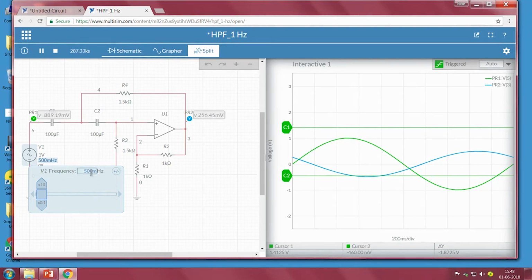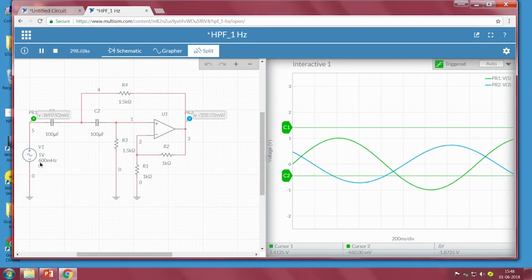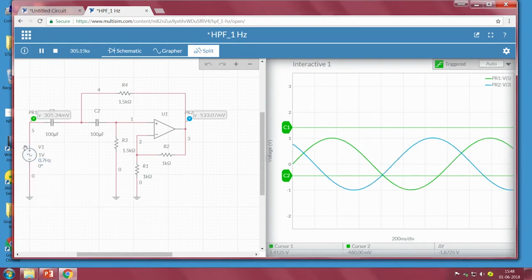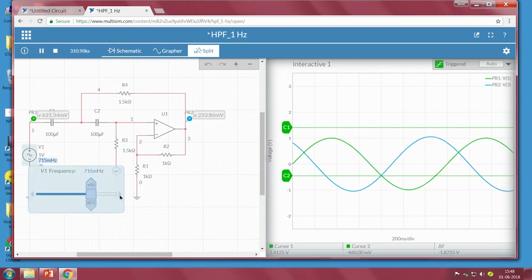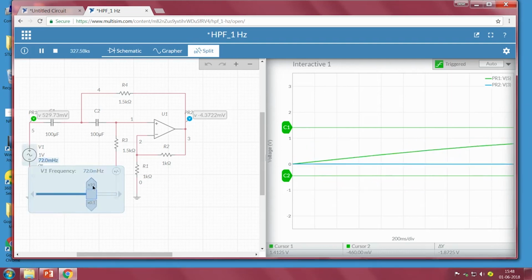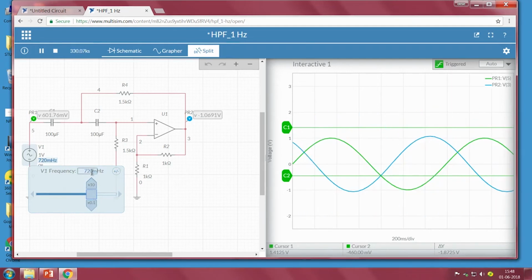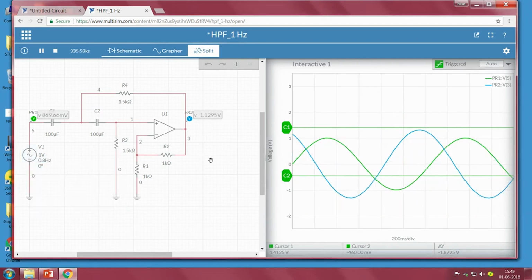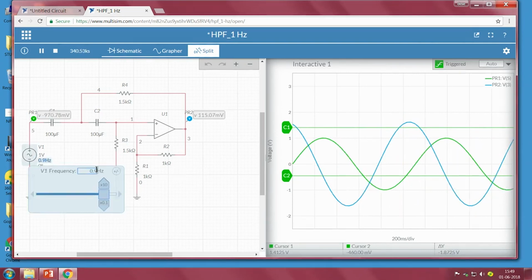In order to understand, I will slowly increase to 600 milli and observe the value, no, then 700 millihertz, not even close, then 0.8, coming close to that value. I will go with 0.9. So, the cutoff frequency is somewhere around 0.8 to 0.9.